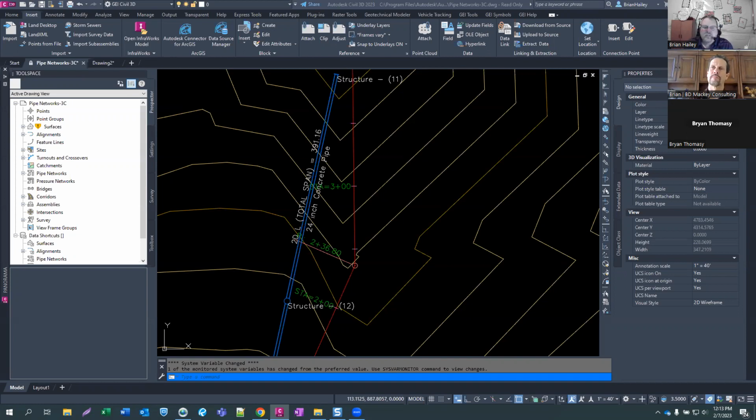Yeah. So I like to classify my drawings as one of 3 different types of drawings. And it seems like every time I talk about it, the names change. But the concept is you'll have a drawing that is your AutoCAD line work. So your existing condition stuff, your proposed condition stuff. This is the stuff that can't be data referenced. Your parcels, if you're using Civil 3D parcels, would also fall into this because you can't data reference a parcel. So you have the stuff that you XREF around, right? And so that's kind of like the line work drawing.